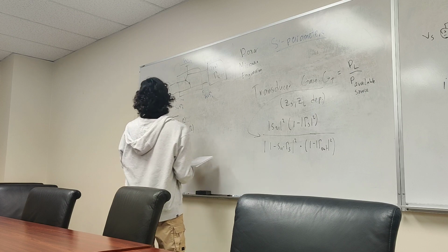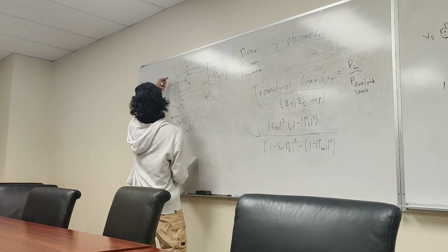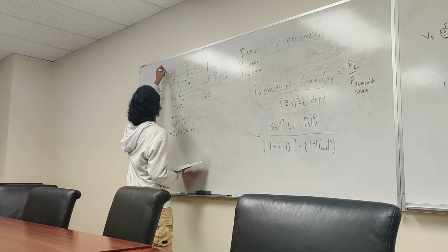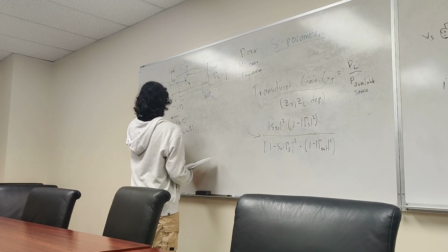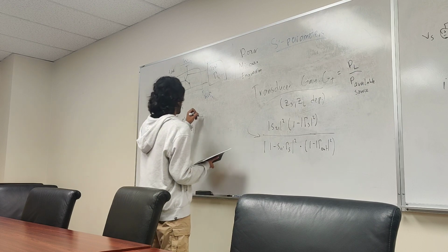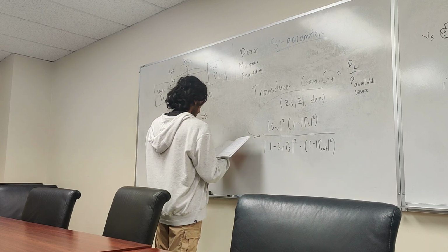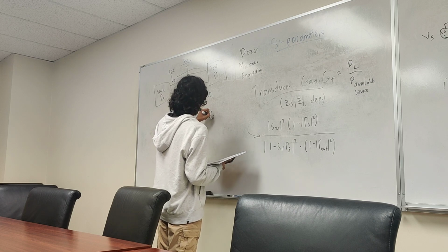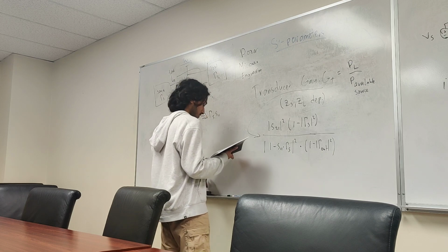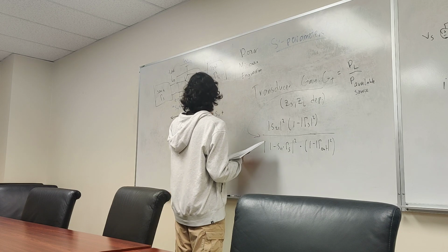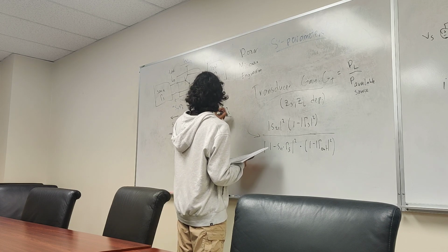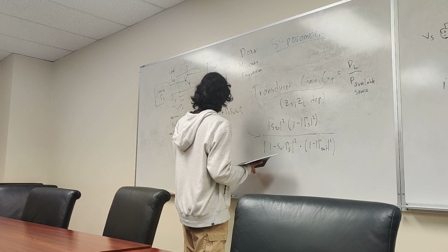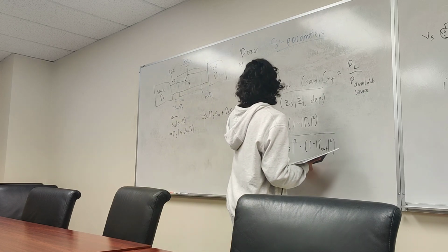So what we're trying to find out is just the total signal that ends up here, right? We want to find this total input signal. So from there, what we're going to say is this initial gamma S, S11, plus this term, gamma S, S12, S21, gamma L. I'm going to erase this now.